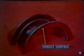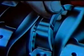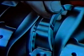On most engines, one of the crankshaft bearings will be a thrust bearing with flanged thrust surfaces to limit the fore and aft movement or free play of the shaft. However, on some engines, individual thrust washers are installed to perform the same function.